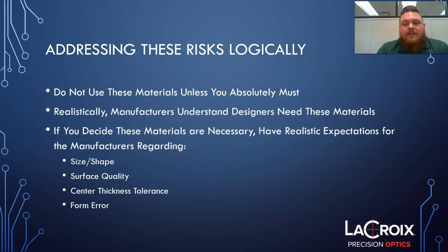Please be critical of it, based on all these risks that I have now discussed regarding these materials. If the optical design system tells you to use these materials, it might be in your best interest and definitely in our best interest if you would go through and try some different materials and see how different the performance may be. If it's only a marginal decrease in performance using a more tame material, it may be a rather considerable increase in the manufacturability of the system.